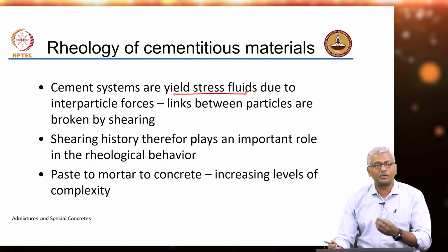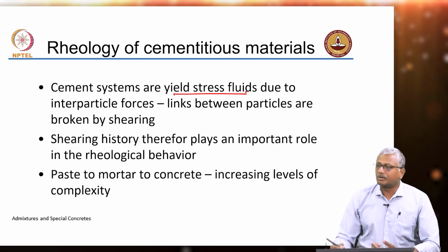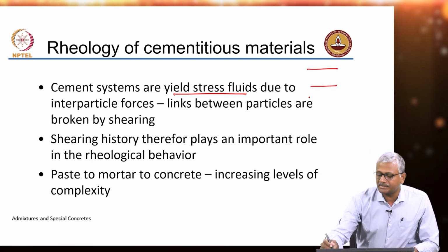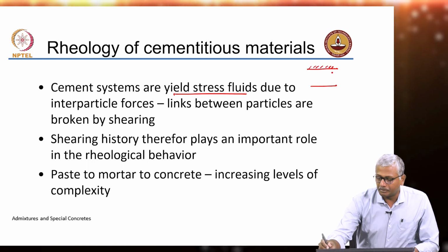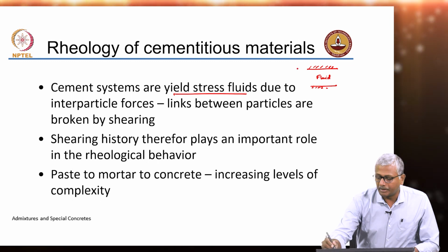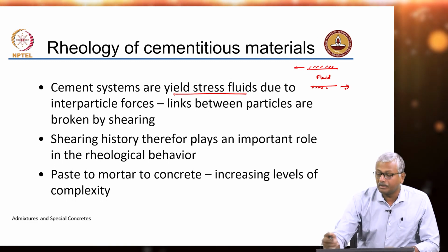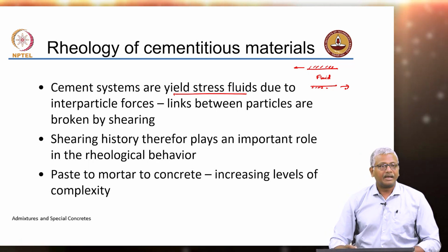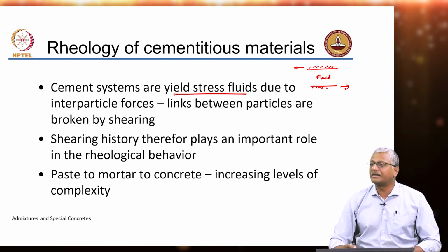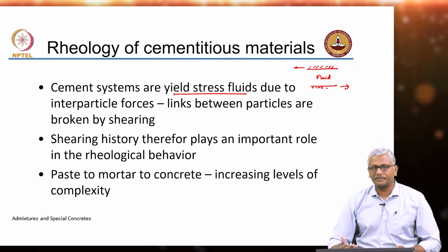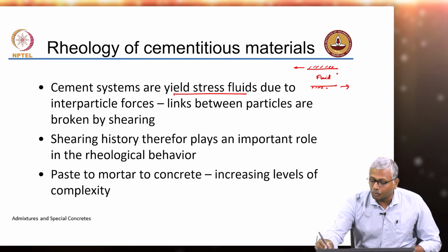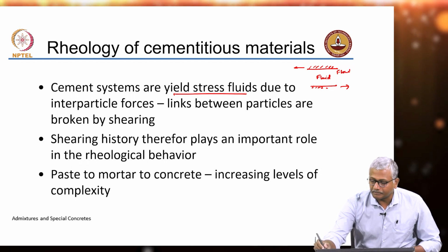Okay, just to take you back to your conventional definition of rheology or conventional definition of viscosity, we remember that we have two parallel plates, right, with the fluid in between, and you are shearing the fluid by moving these plates past each other. That's a conventional definition of viscosity, and you define viscosity as the gradient or slope of the stress versus strain rate curve when the flow is laminar.